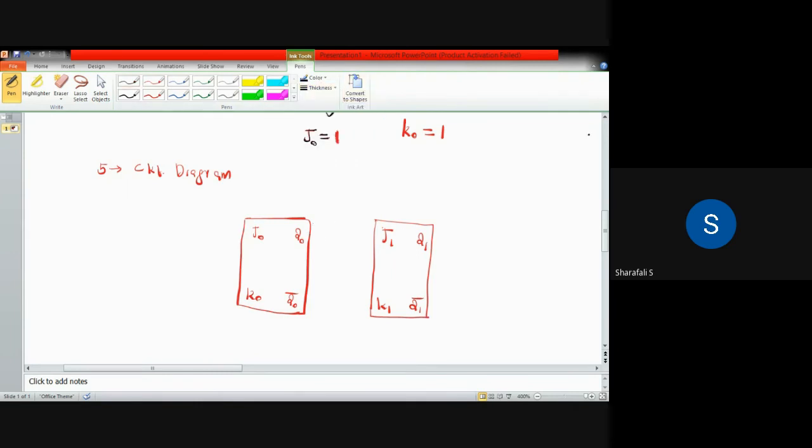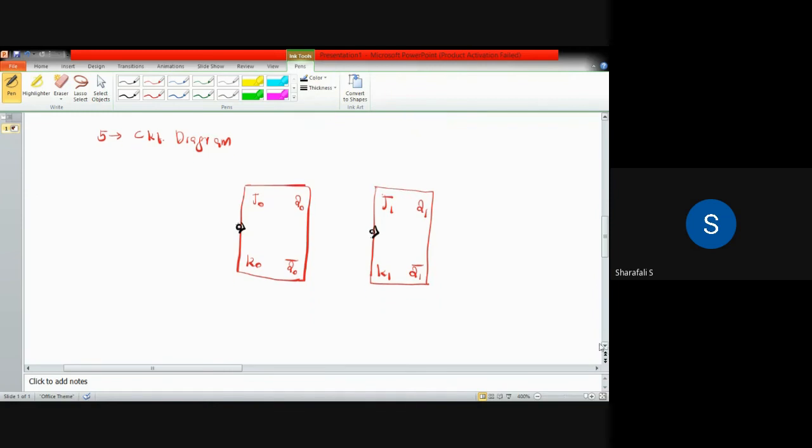So as you know, for this synchronous case, we have to apply the clock pulse to all the flip-flops simultaneously. So we'll give the clock pulse to all the flip-flops at the same time. Here we are considering a 2-bit counter, so only 2 flip-flops are there, and we have the clock connected here.